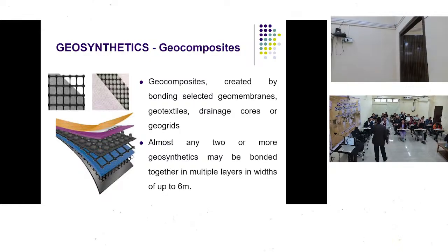So they wanted to contain the water in that dam. What they did on the whole upstream face of the dam was install a geomembrane. Suppose this is the dam face; the whole face they installed a geomembrane. For example, this particular banner is also a geomembrane, but we don't know its tensile strength, we don't know its permeability, and we don't know what load it can take.